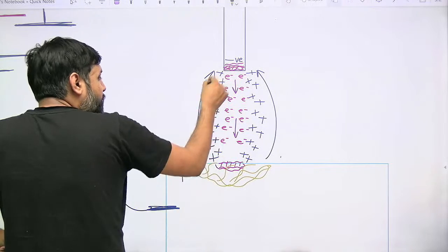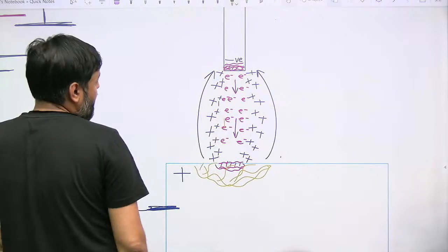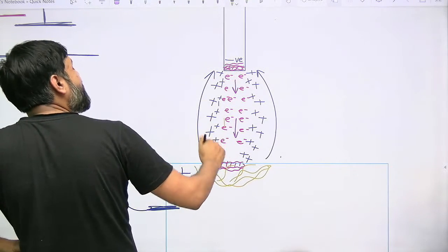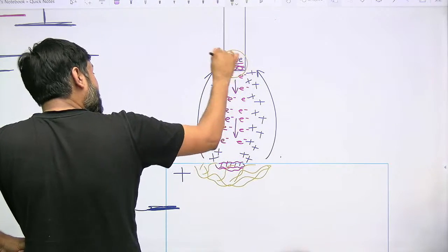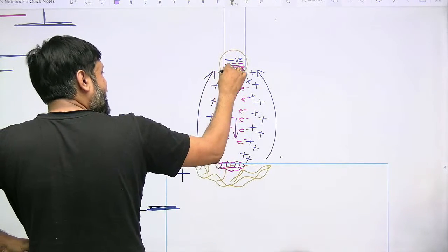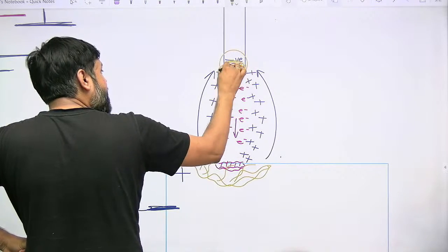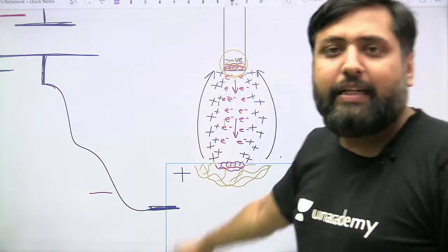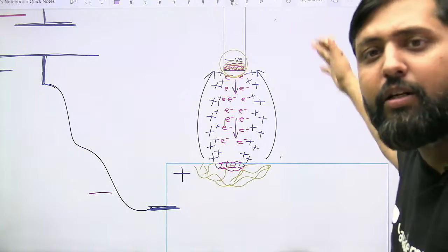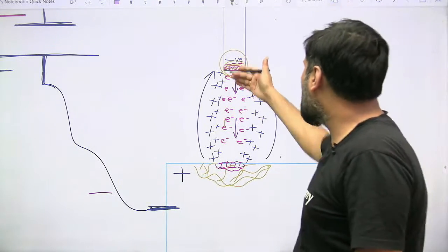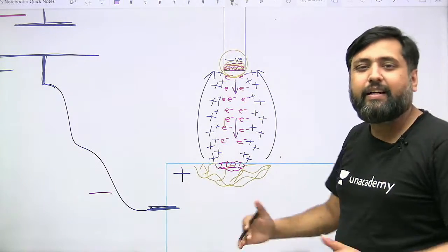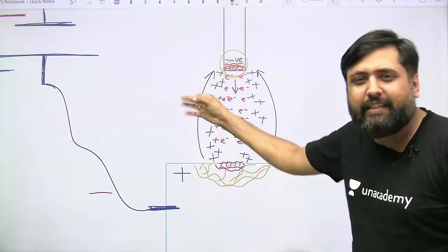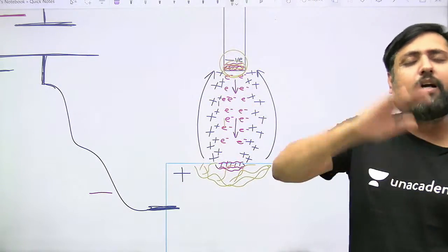And my dear lovely students, these positive ions all around are traveling from the positive side towards the negative side. So when positive ions collide with the negative side, which in this case is the electrode, their kinetic energy will convert into heat energy over here and the electrode will melt, and that is how welding will progress. This process will continue because the electrode and workpiece will get heated continuously, and emission of electrons and ions will keep happening, and this phenomenon will continue.